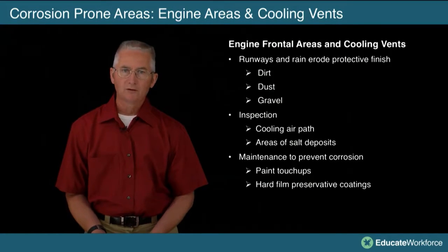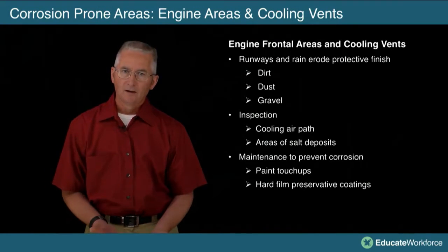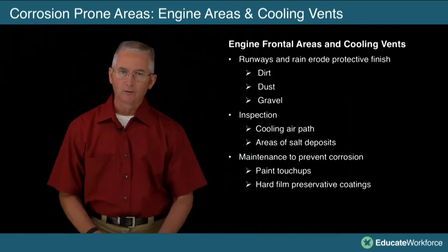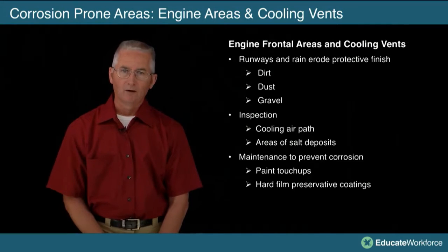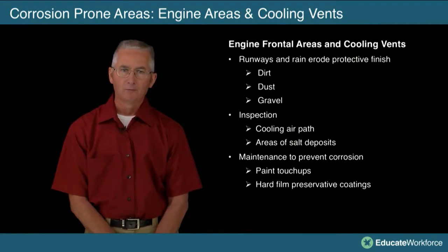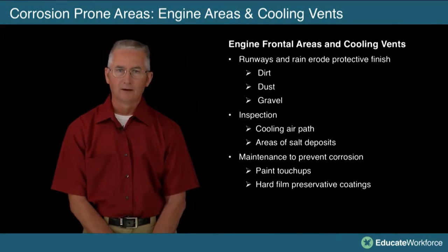Sometimes if moisture gets underneath the paint, over time you're going to start to notice the paint bubbling and blistering. Good indicator that we've got something going on under the paint, and it's time that we start removing that paint and looking to see what's going on.